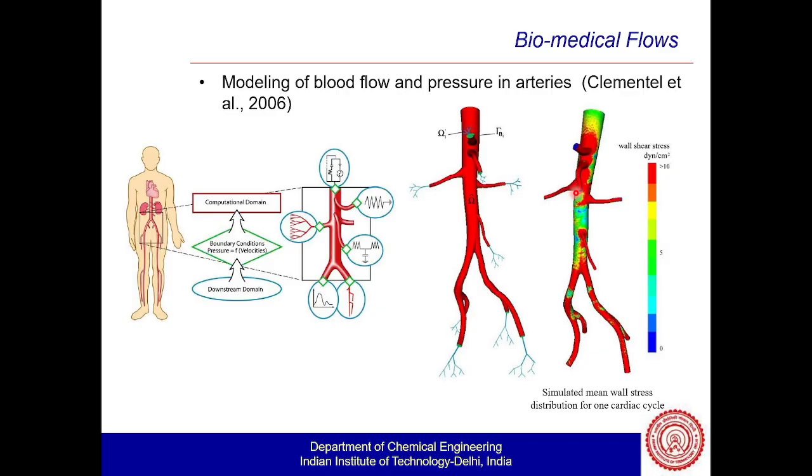You have to discretize that for each and every cell, and then convert it into a system of linear algebraic equations. That will be converted into a matrix. From there you have to find what is A, what is B, and then you find X, because X equals A inverse B. That's how you build it. The basic structure remains the same. Do others have any questions?